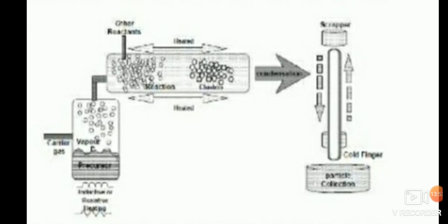It is readily found that the residence time of the precursor in the reactor determines if films or particles are formed. In a certain range of residence time, both particle and film formation can be obtained.